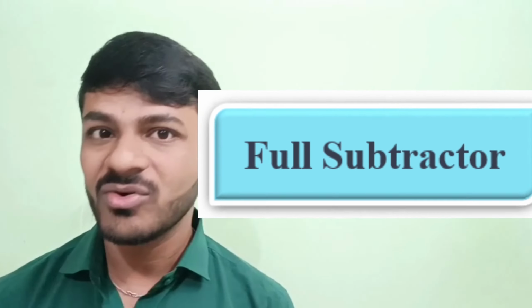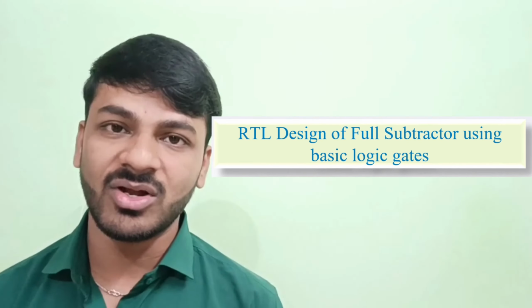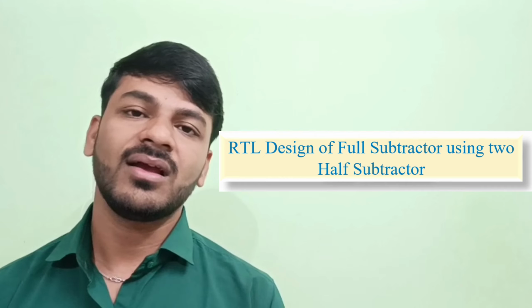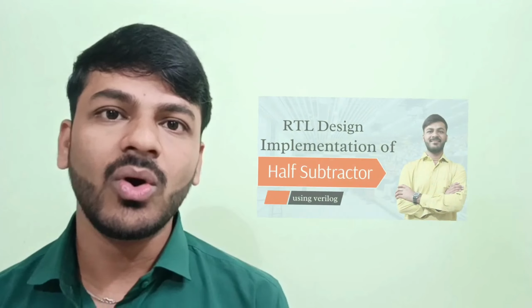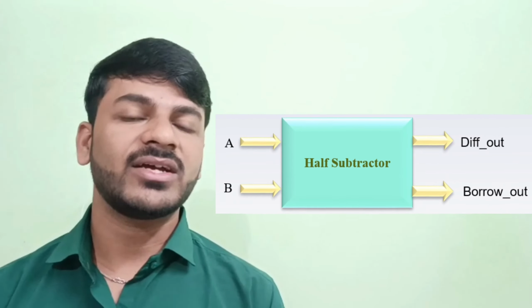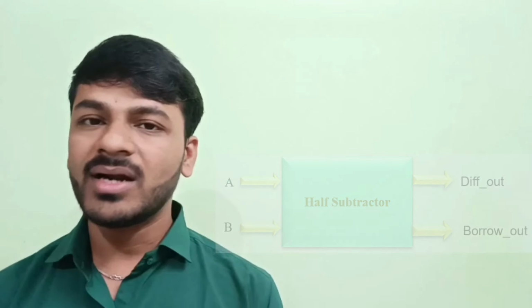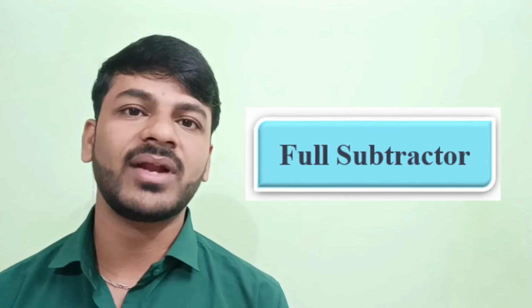So basically in today's video, we are going to discuss the full subtractor and the RTL design implementation of a full subtractor by using basic logic gates, and by using two half subtractors. In my previous video, I already discussed the half subtractor, which is useful for subtraction of two binary numbers and gives us a difference and borrow out. But a half subtractor doesn't handle borrowing from the previous subtraction. So to overcome this issue, we now have the full subtractor.